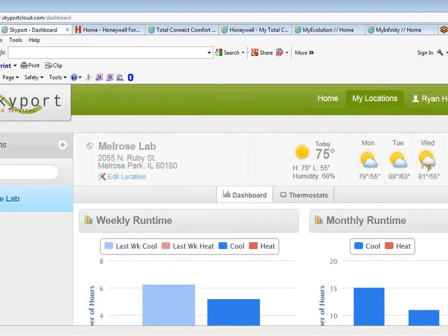So if you had a two-zone, say two-zone Honeywell panel that's controlling air zone dampers, you could put two of these stats, one on each zone damper, and each one of them would be independently controlled just like they would be if they were on your wall.